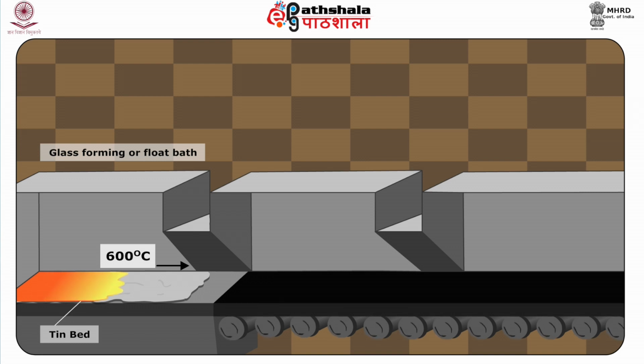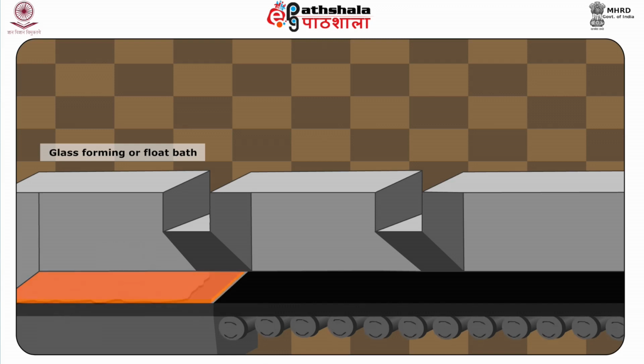In other words, it is the steady and constant change in viscosity with respect to temperature which permits molten glass to be converted into a large number of products. Thus, in an appropriate range of viscosity, molten glass can be subjected to many different processes to make products ranging from flat sheets several square meters in area to filaments with a diameter less than that of a hair.